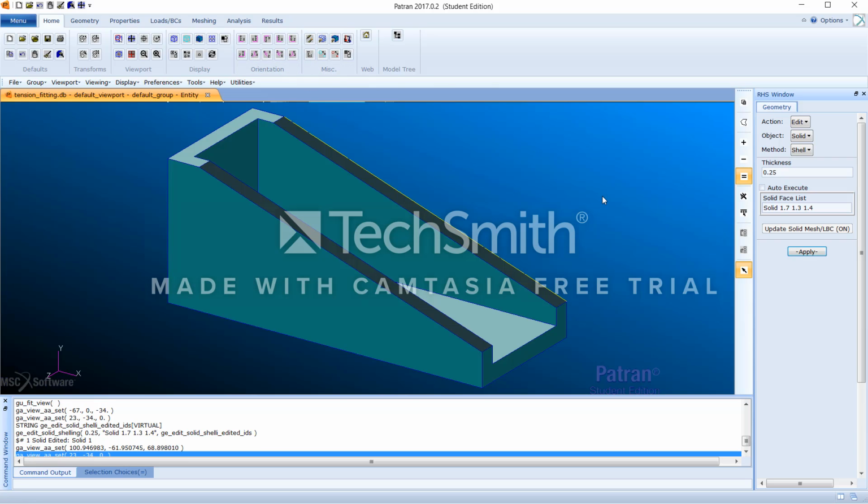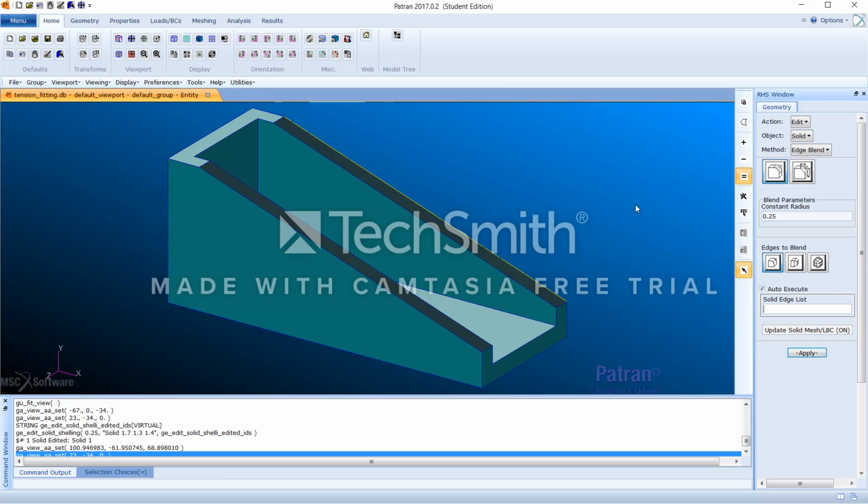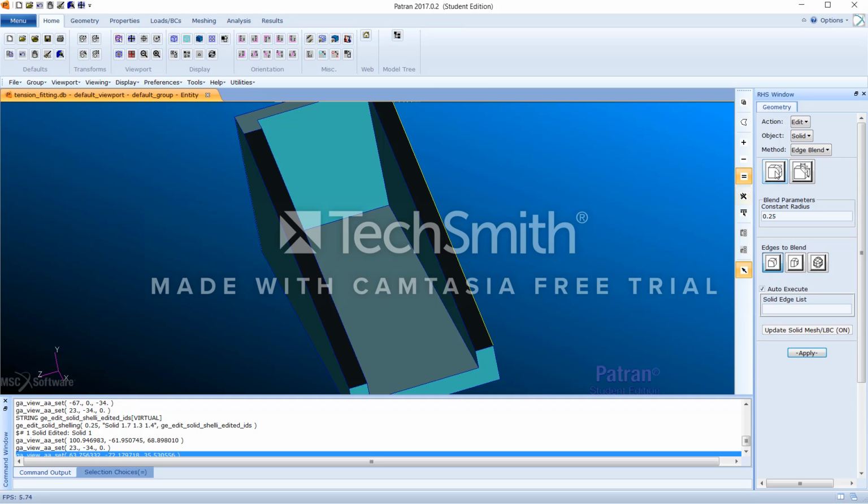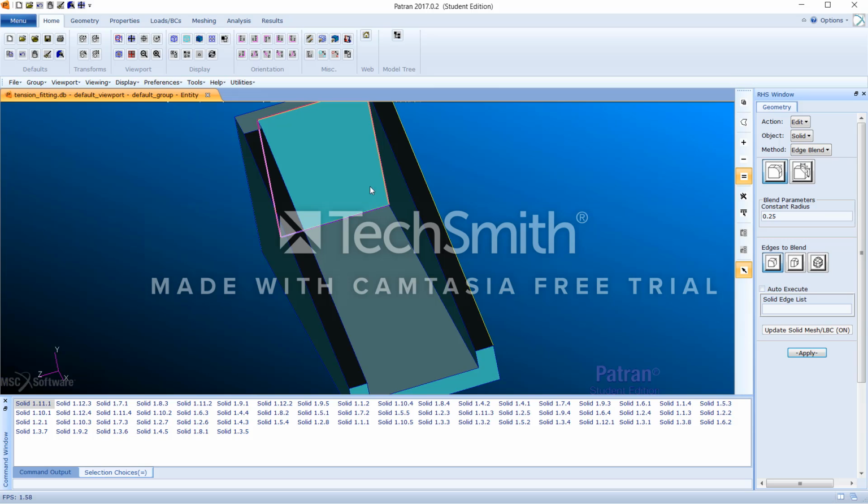We'll do some fillets on the inner edge of the solid. Set action as edit, solid as object, and edge blend as method. Select the constant radius icon and enter 0.25 for constant radius. Select edge of solid icon, turn auto execute off, and select the 5 edges of the solid inside and apply it.